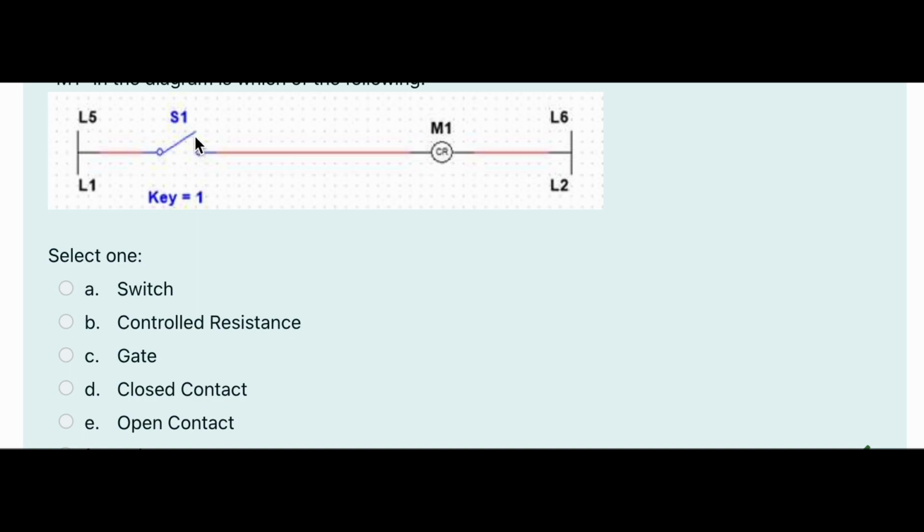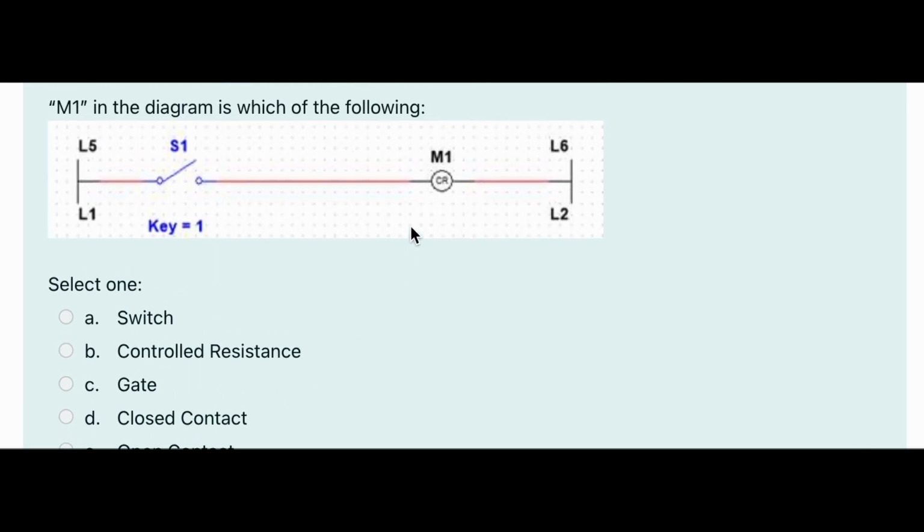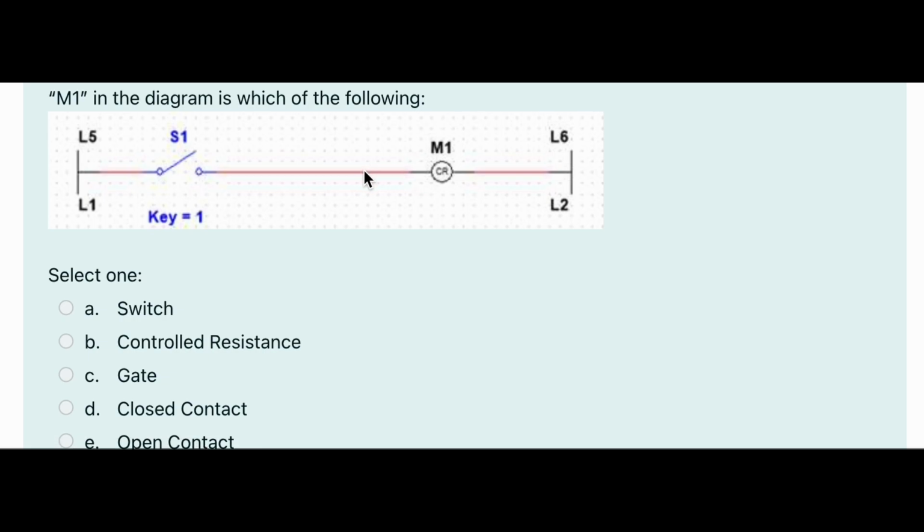The switch itself is going to be this part right here. It's going to be a relay because it's going to relay whatever signal we have here, because currently with it open, there's no signal. Once this closes, there is a signal, and it's going to relay it to the actual NC, which is normally closed, or NO, which is normally open switch for our ladder logic.